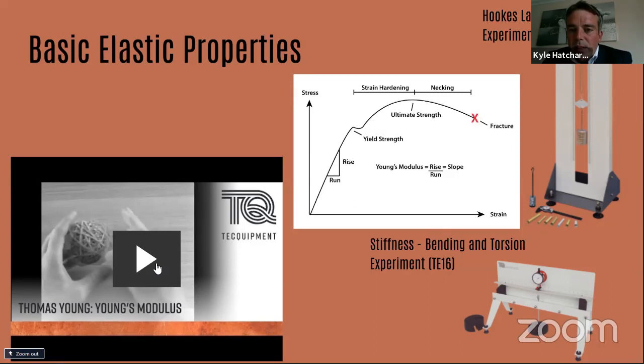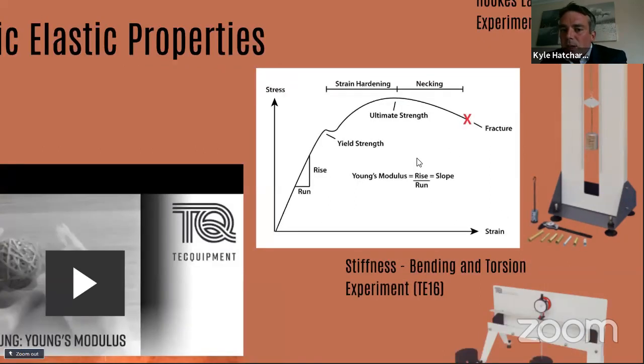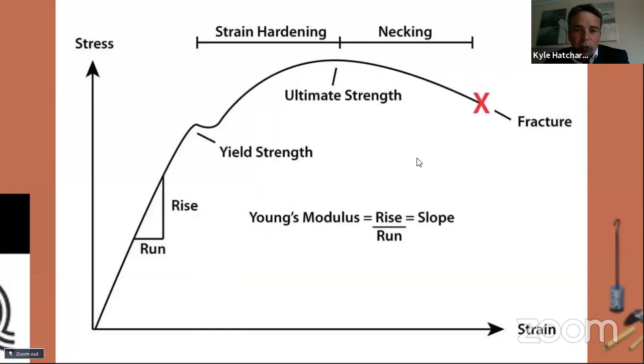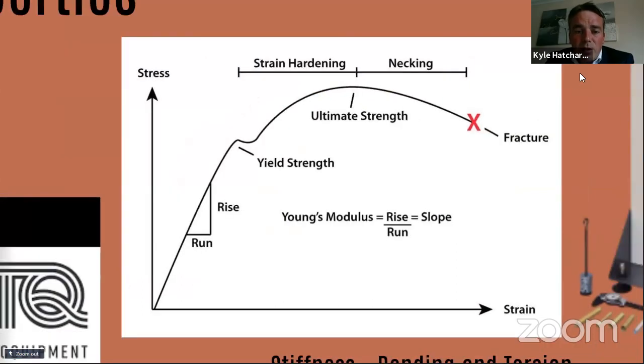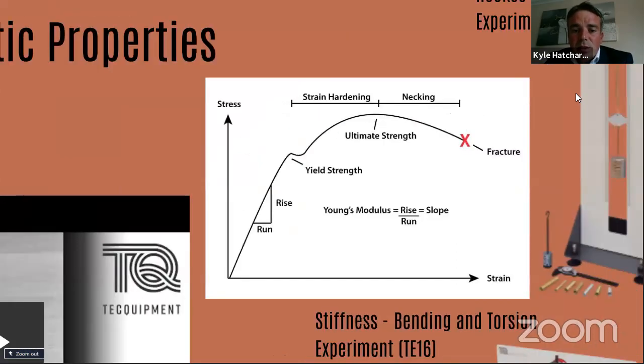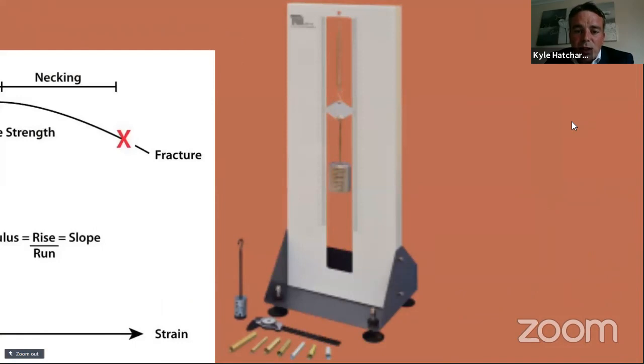So you see the elastic limit, that's the linear rise in that curve from 0 to where it marks out the yield strength. And that's effectively identifying Hooke's law again. That brings you into the SM110, which is basically understanding how springs work, where a material in that region is able to return back to its original shape or form.